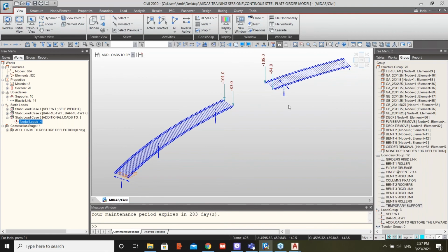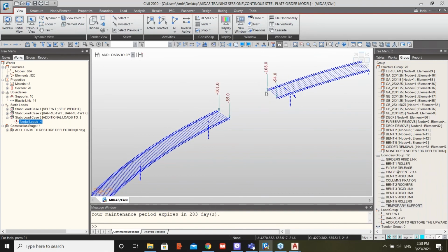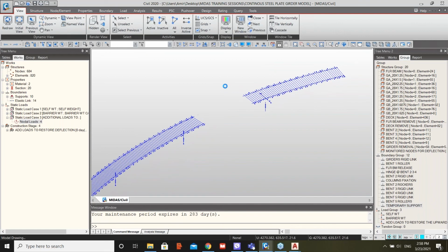You see, this problem is sophisticated because it is a statically indeterminate structure, and you are also removing part of the span, so you are changing the statical system of the structure. So we ended up having different loads at each tip. A problem like this is really difficult to solve by hand. You cannot do that. It's very important to use finite element analysis for that. And of course, employing the construction stages is very important to predict the response of the structure accurately.